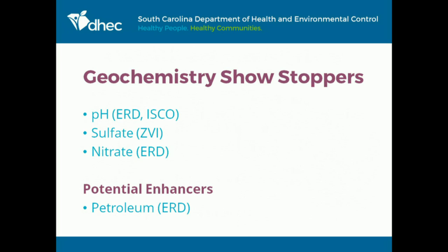Sometimes we have found petroleum products in the subsurface actually assist reductive dechlorination. We have some dry cleaning sites next to gas stations that have cleaned up amazingly well. It's primarily because of the petroleum and co-metabolism that happens when the petroleum is present and the bugs are there eating the PCE. It stimulates those bugs, and it actually gets down to ethene without having to go through the process that we normally associate with it. I'll take questions at the end.